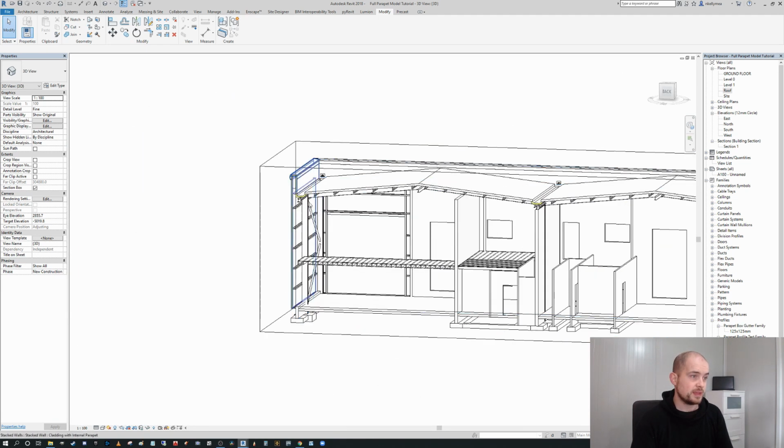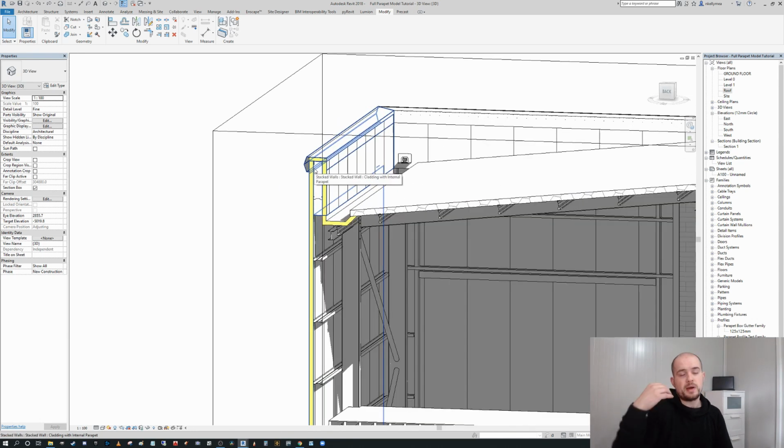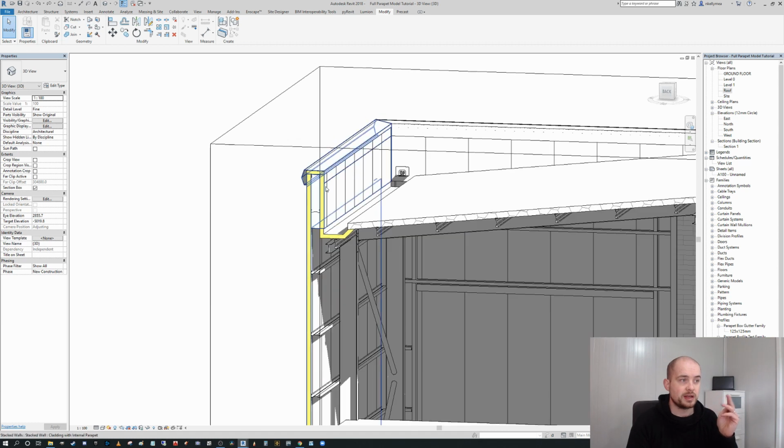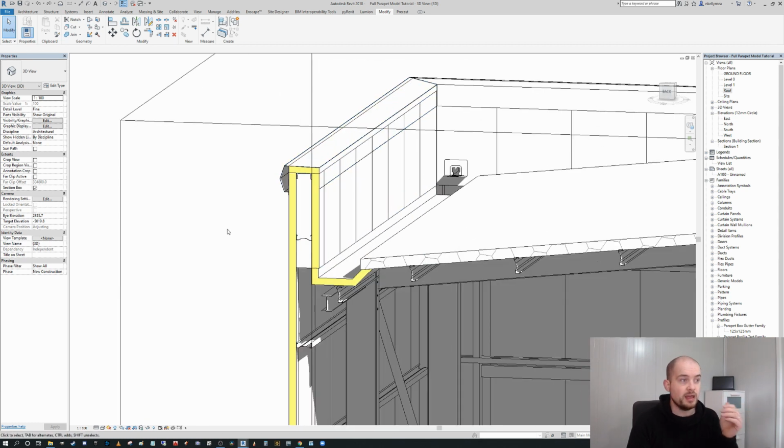Okay, so that is my preferred way of modeling a parapet capping if you have something like a stacked wall, as we have in this instance. If we had separate walls, I may consider not doing this because I'd only be applying the capping to one leaf, and that can be a little bit temperamental. We could end up in a situation where we have a variation between the leaves and our capping has to vary, but we've only got the internal wall, let's say, with the capping sweep on top of it. You can't vary that per instance then, okay? It would be a type property that would drive the whole thing. So in which case you might need to do part wall capping extrusions all the way around.